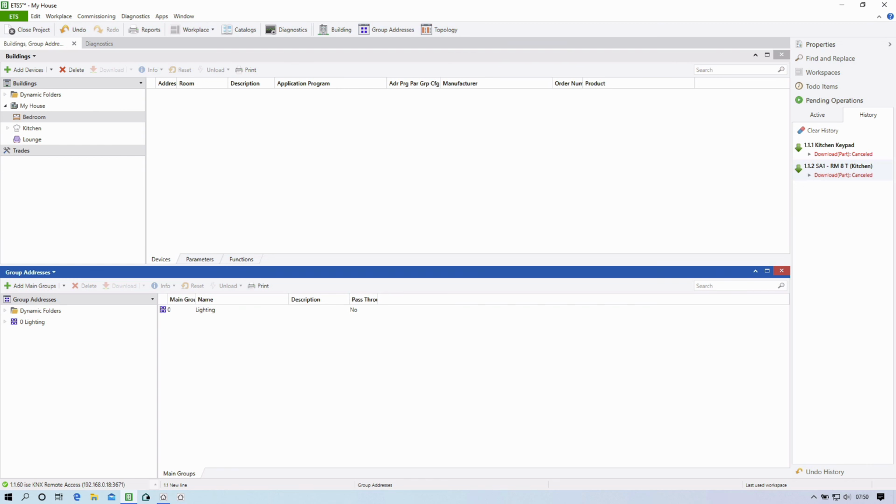Right, that's it for this introduction to ETS video. Hopefully that's given an idea of how you can use ETS to create a project and some of the steps you'll need to take when it comes to programming. It's a pretty powerful program with lots going on. There's always lots of different ways to do things. So it can be a little bit intimidating at first, but it really does start to make sense when you start to connect to products and download and start to see things happening.